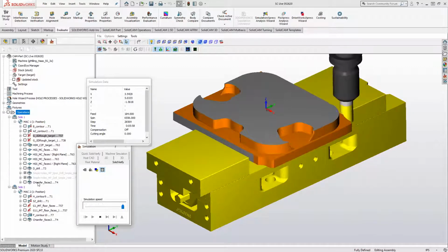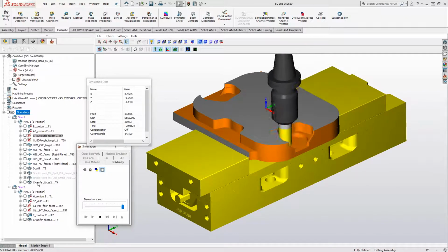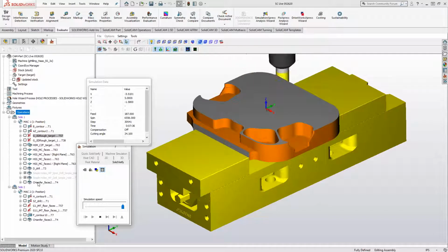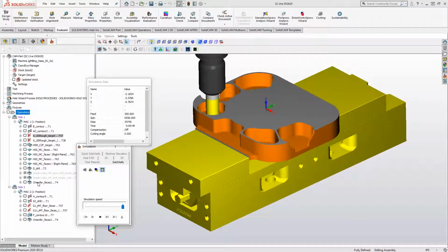We can see that there's no gouges. And one thing you guys can also remember too is, let's say that center of that bore, we have plus or minus 0.2. So at the end of the list, we're going to add another probing operation just to take a measurement off that probed hole. And then for the next part, if you guys are running production, it would automatically adjust that comp if you guys are running like the Haas controllers and stuff like that. And that could have also been a copy of one of our other probing operations, right? Okay. We could have just changed the parameters.